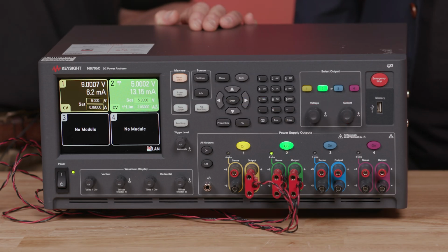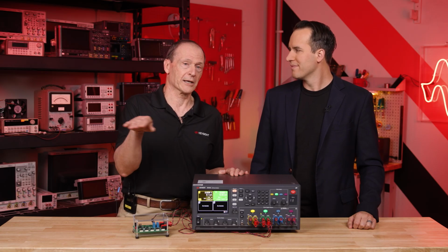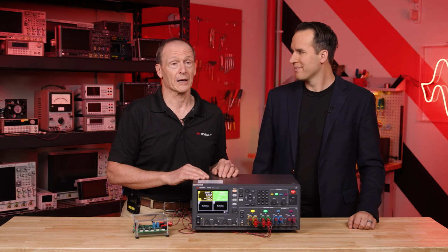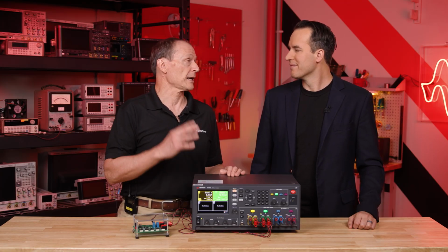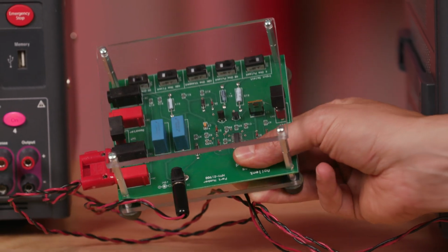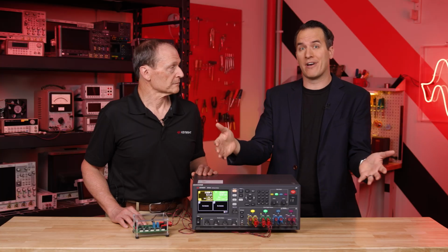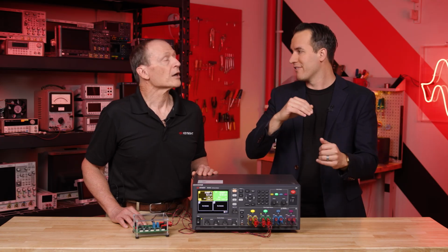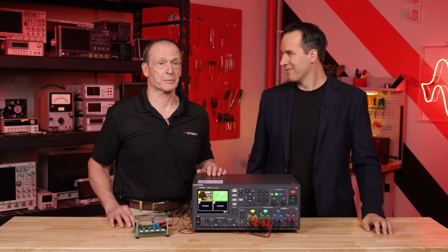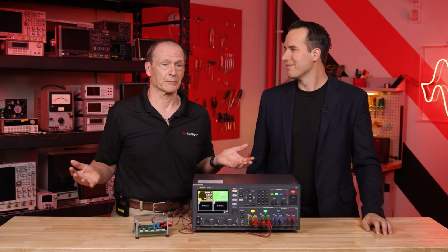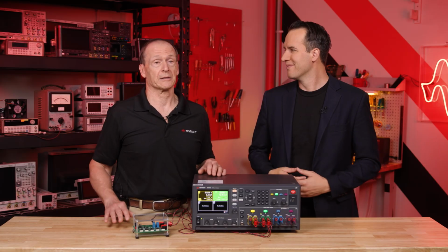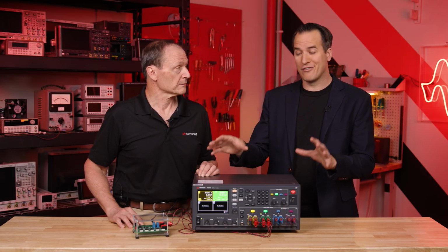And you're going to expect to see some waveforms. Essentially it looks like 0 amps of current, and then you're going to see a spike that's about 120 milliamps. And as I'll show you in a minute, when you go down and look at the low levels of current, you're going to see a bunch of noise. So we'll be able to see how much power the device is consuming, and then we'll get a snapshot of the current output in those different states. Correct. And we're going to be using the scope mode for this, but as I like to point out, you can also do this in the data log mode. So if I wanted to look at this device for minutes, hours, even days, I could take a data log of that, and I'll actually see both the high and low levels of current. So great for characterization. Let's take a look.